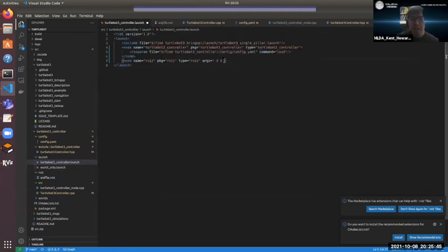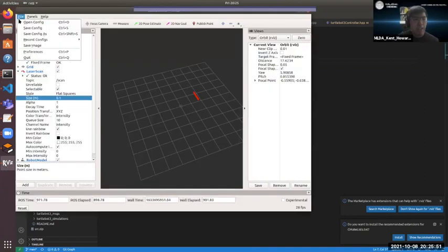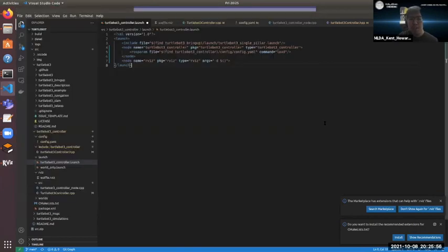And how do I load that config for RViz configs? If I'm not mistaken, there's a way to load it here also manually, but you can also do it with your launch file by looking for the RViz file, which is in my turtlebot3_controller package inside the rviz folder, and I called it waffle.rviz.